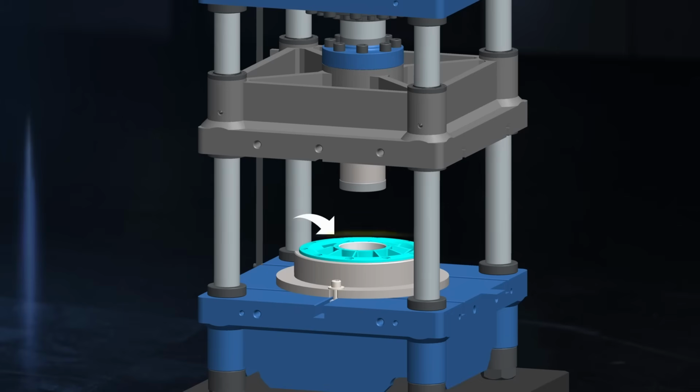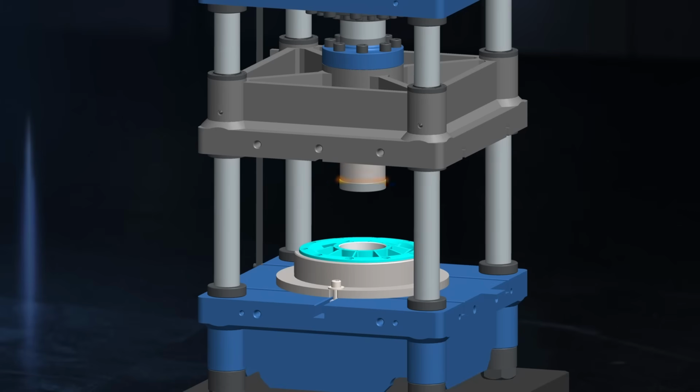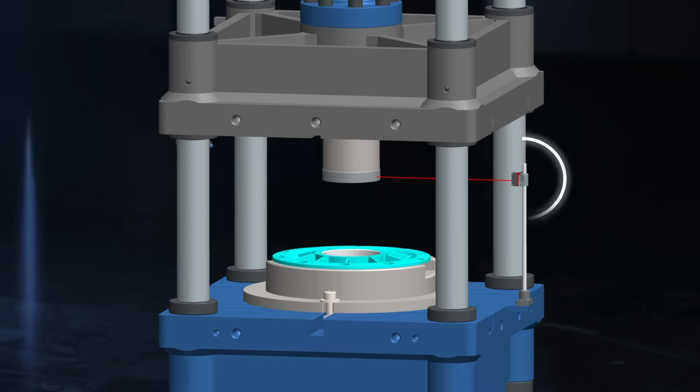Now, in any automated assembly machine, before actual operation starts, the machine first checks whether all parts are properly placed. Because if any part is missing, it can damage the machine tool, the fixture, or the top tool, or maybe it could damage the child part. Or maybe the product will get assembled but without some missing parts, which we don't want at any cost. So to make sure that all child parts are present and correctly positioned, we use part present sensors, or we call it job sensor.